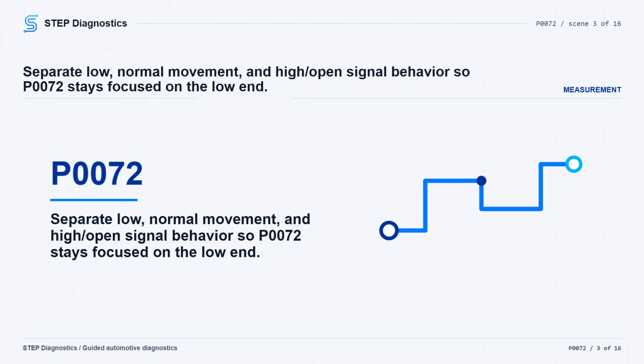A voltage reading above approximately 4.9 volts would set a circuit high or open fault, and a voltage below approximately 0.10 volts will set a circuit low fault. For the circuit low setting point, the sensor signal voltage is below a calibrated threshold, typically in the 0.1 volt range. For the circuit high setting point, the signal voltage is above a calibrated threshold, typically in the 4.9 volt range. Circuit high and low faults are monitored with the ignition on and battery voltage above a calibrated threshold.